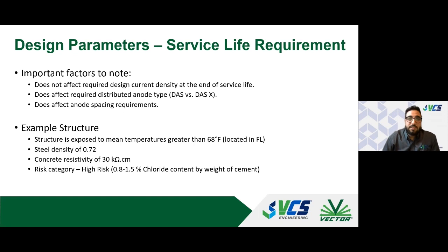Service life is obviously another important factor, because that can significantly affect the type of anode and also your spacing and your design. The one thing service life doesn't affect is the design current density required at the end of service life, and what current density you design with. However, it would affect the type of anode as well as its spacing.